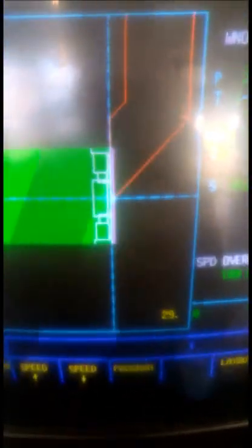You can speed this up or down. So we've got a face cut, and then a finishing cut on the face, and at 100% speed this will show it in real time. So you can see if you've got some speeds and feeds that are ridiculous. So a rough cut, finish cut. In comes, now that's obviously, I've set that wrong in the tool data. It thinks that's an internal tool. That's cool. So spot drill and then a finishing drill. My 12mm hole.